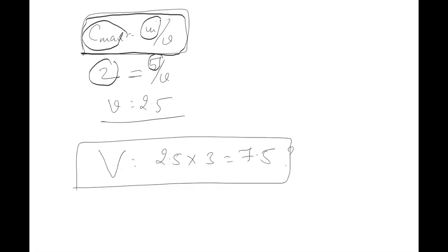Step experiments may not start from origin. Reason: when you start the red fluid, the reactor is filled with white fluid, no? So that white fluid has to go out, then only red will come out of the reactor. Yes, it should be mentioned in the question whether it is a pulse or step experiment. The curve may not be a straight line sometimes. In GATE questions, you will get straight line equations. Generally in your labs, you will not get a straight line equation. So in your lab, the area is found by the trapezoidal rule, Simpson's rule, or, if you are plotting on a graph, you will count the boxes.